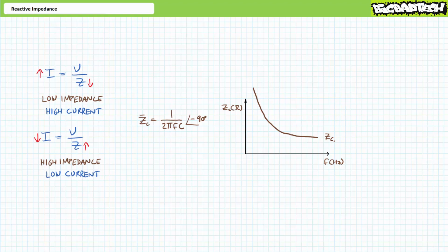Now that we've got an understanding of how frequency affects impedance, let's discuss how capacitance component magnitude influences impedance. Capacitance is in the denominator of the capacitive complex impedance formula. Given constant frequency, high capacitive elements present low impedance, whereas low capacitive elements present high impedance.